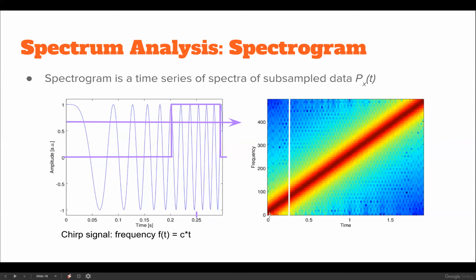Voice recognition is hard to do only in time space, since these signals are sinusoids, and you know what happens if you, for example, try to calculate the product of two sinusoids and integrate it. Most of those products will be zero, so it's hard to make the correlation analysis of that kind of signals, but it's relatively easy to do the spectrum analysis, since after all, voice is not carrying time-based information, but spectrum information.